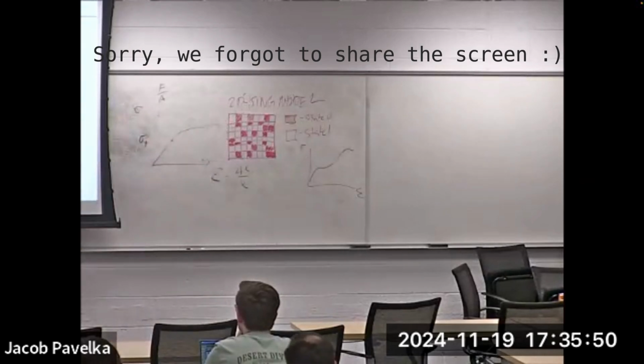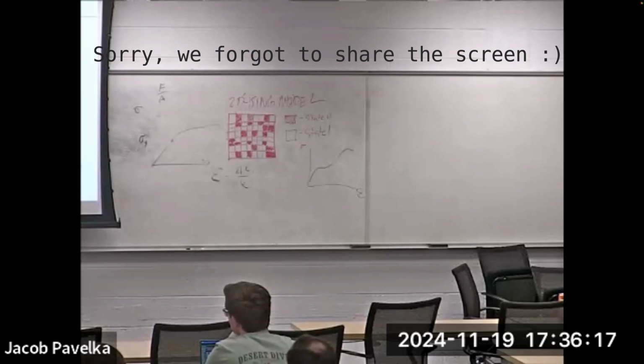And kinematic hardening is something else. If I pull it in this direction, and then I want to bring it back and maybe compress it, the amount of plasticity that's accumulated when you pull it will have some effect on its behavior when you compress it, because the material has gone under some of this permanent deformation. That's called kinematic. Last couple things are just a couple algorithmic details, so I'll skip that.